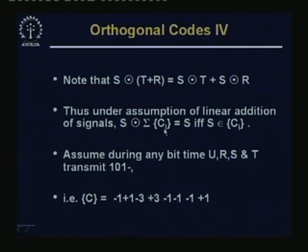That means, suppose there are a number of channels which are transmitting. There we have already assumed linear addition of signal strengths. So this is nothing but the sum of the signal strengths like T, R, U etc., they have all been added up. Now, S dot will distribute over this summation, so we have S dot T and S dot R etc. If S happens to be in this set Ci, then that S dot S will come out as 1. So it should be 1 if and only if S is in Ci, otherwise it will come out as 0.